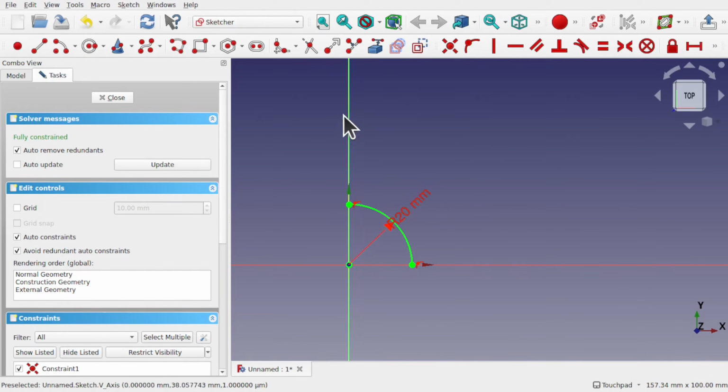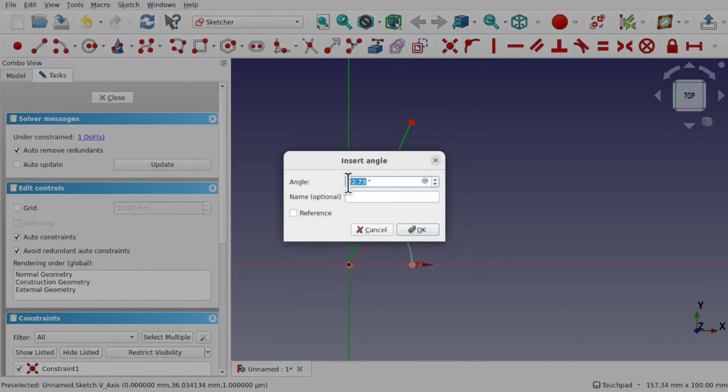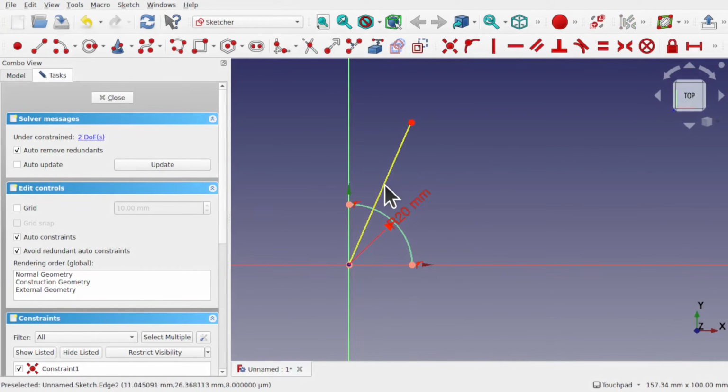We're going to use the vertical and the horizontal axis guidelines. If we've got a different fan and it's smaller, then we can add some lines in here and set angle constraints between these two with an angle constraint and set our angle up in here. And we do the same over this side as well with the same angle. But because I've got 3 blades, I'm going to just use this quadrant. So I'm going to create 2 more lines now and place these connecting up to the vertical and the horizontal like so. And we're going to create another arc.